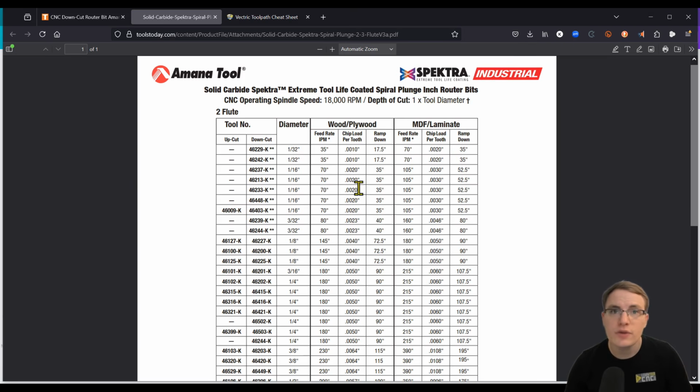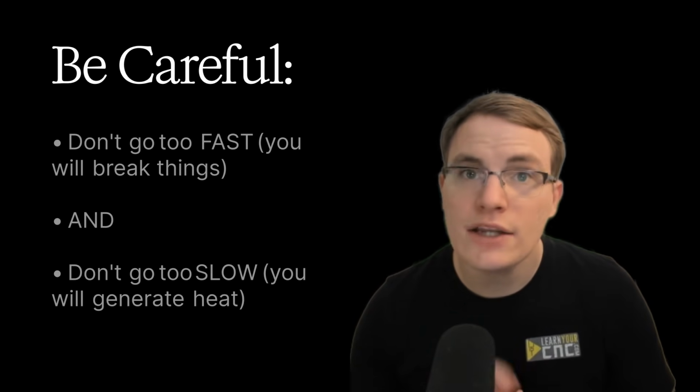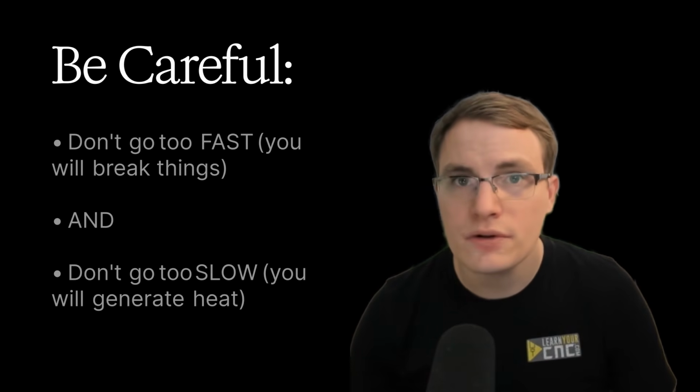Now you do have to be careful with these feed and speeds. As you can see in the top right corner, this is for industrial setups. So a lot of these feed and speeds are not going to be as useful for those of you using a smaller hobby machine. You can use it as a general reference. However, just be careful you don't go too fast, and you also have to be careful you don't go too slow.